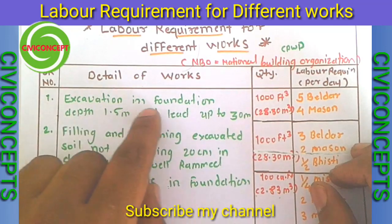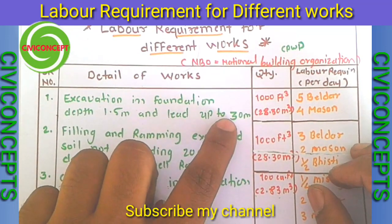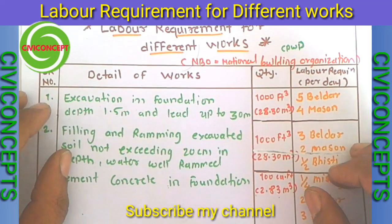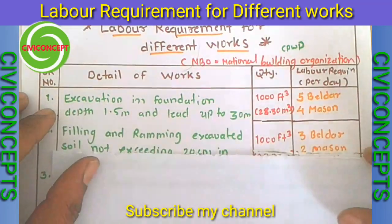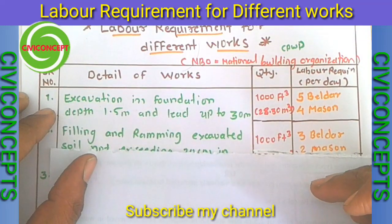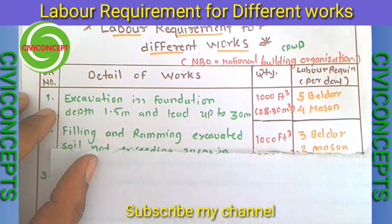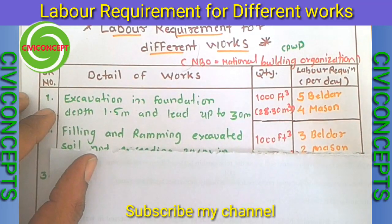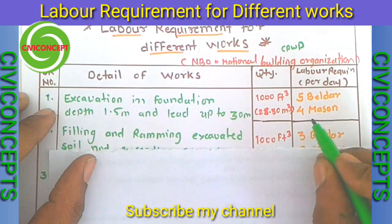First is excavation in foundation, depth up to 1.5 meter, lead up to 30 meter. So the work is that we have to excavate in foundation up to 1.5 meter and lead up to 30 meter. It means whatever material you excavate, you have to throw it at least 30 meter away from the edge of the trench. For that you require 5 beldar and 4 mason.